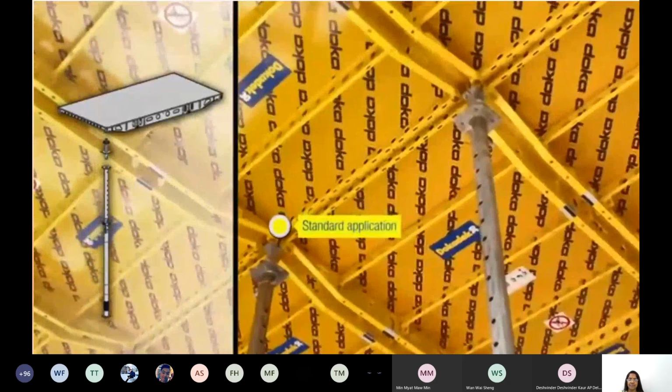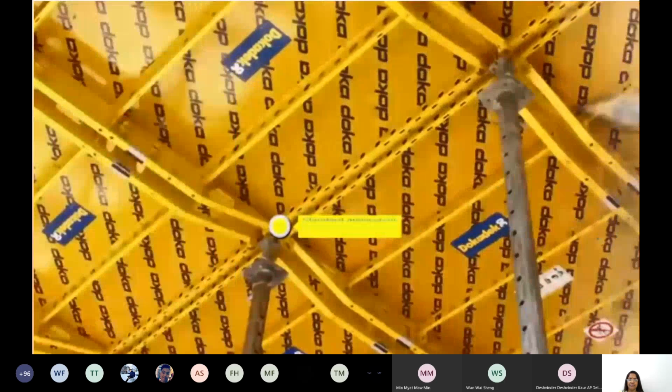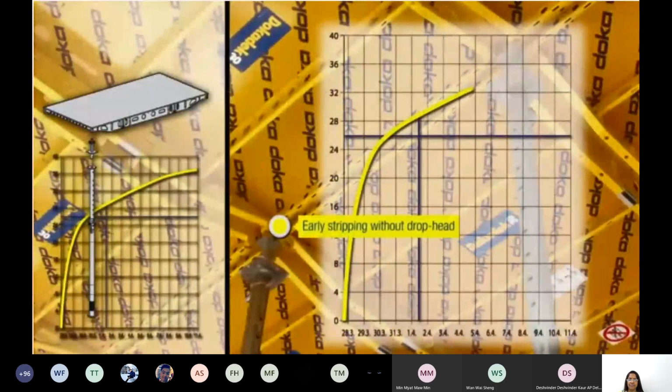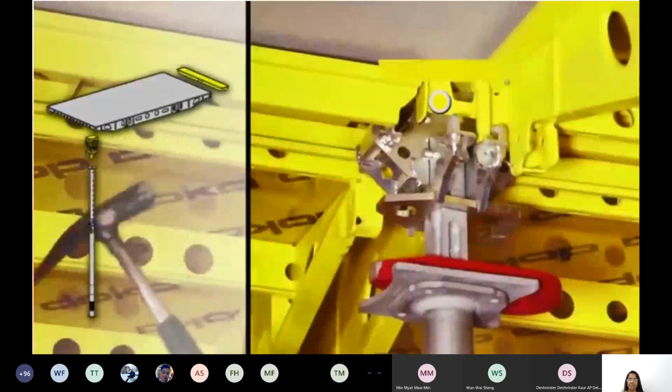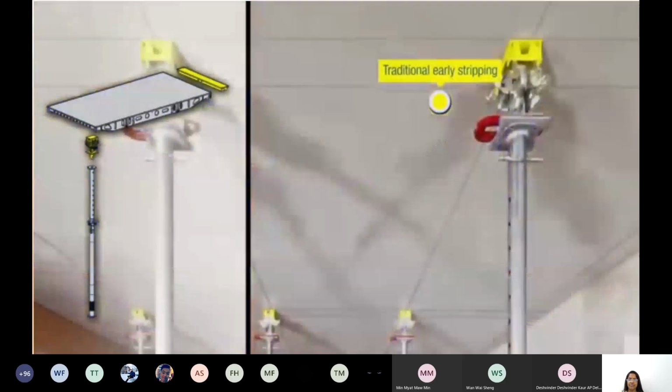Well, one of the safety features we have is that the large panel, which is sitting on 2 galvanized steel props, has an anti-dropout device built in, so the panel cannot drop down on its own. It has to be lifted up and then moved away from the props, which ensures that there's not that danger of something falling on anything.